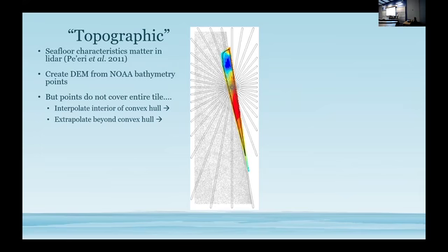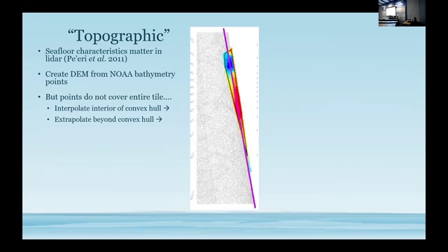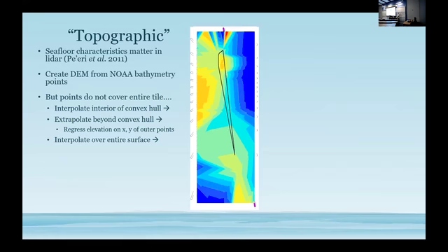So to do that, for a typical tile, I take that one and extract the points that are at the very edge of it, which you'll see there. Once I get those, I regress X and Y out to the Z direction out here, assuming a linear relationship on those ends. I also double check to see if the root mean square error is too big for that particular regression. If it is, I don't use it, because I don't actually need all those points. And then once I get that, I can go back in and I have points at the exterior.